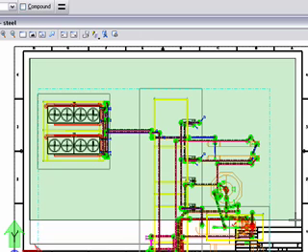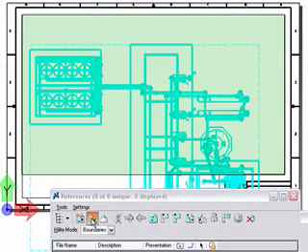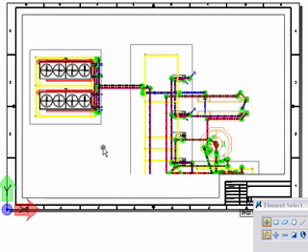In this case I'm going to do it very simply, and then I can come down to my reference settings and say clip reference. Let's move that up a little here. I can say clip reference, and now once I've clipped the reference, you can see that my drawing itself has been clipped into my sheet file, and now we have our drawing that's ready to produce.